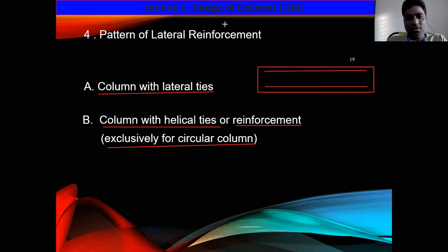This is the longitudinal bars. Then we have given these, which are the shear reinforcement, because in beams we have designed the shear reinforcement also, which we call stirrups. The same ring we designed in beams we will use in columns, but the name changes to lateral ties.